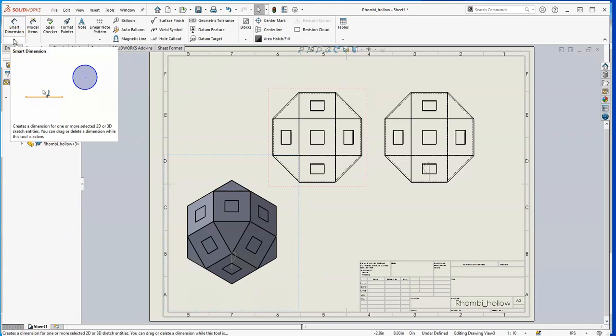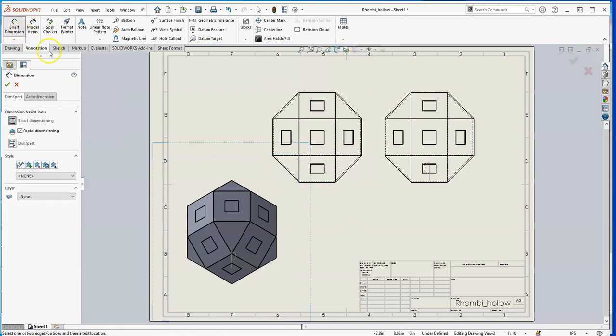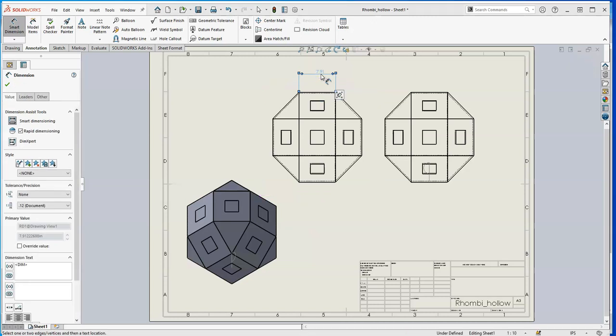Next, we want to put some dimensions on it. So if we're going to get this built, we're going to need to have dimensions on it. So if I click on Smart Dimension, and I want to give the length of this side here. Okay, that's coming out as 7.91, so something's wrong with that. We said it was around 200. Go down to the bottom right. It's in inches, pounds, and seconds. I'm going to change it to millimeters, grams, and seconds. Remember, we originally set our length to 196, but it's been projected out, so it's over 200 now due to the projection outwards.